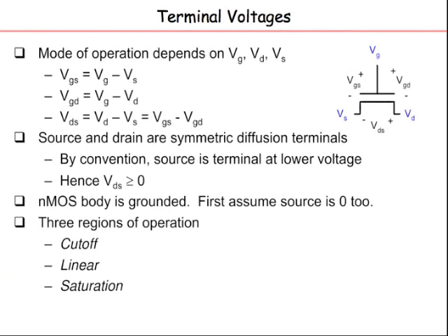So that's basically the important aspect here for the transistor from the point of view of currents as a function of voltages. So you have three nodes: drain, gate, and source. You also have the fourth node, which is the body, which I already said, for digital, you typically connect to ground for nMOS and VDD for PMOS.